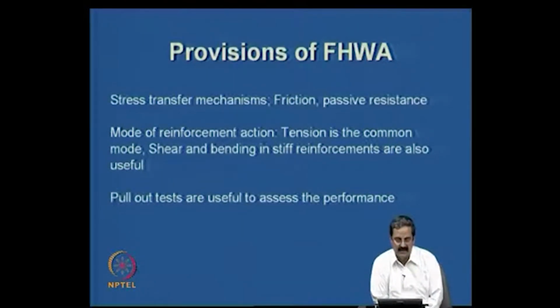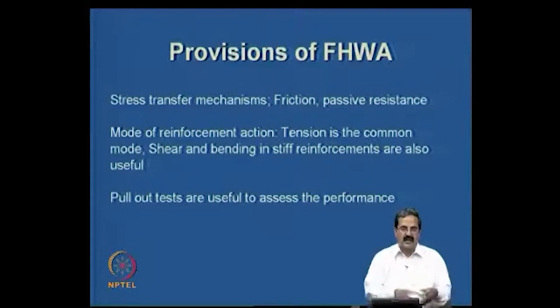design better structures. Then another important test that we need to conduct in most of these cases is the pull-out test. So pull-out tests are very important. In fact, for geogrids, geotextiles, something in the field, you can pull out and see pull-out load versus deformation is what you get actually. Then you will be able to assess its long-term performance and short-term performance also. Short-term performance is in terms of its force mobilization, right?